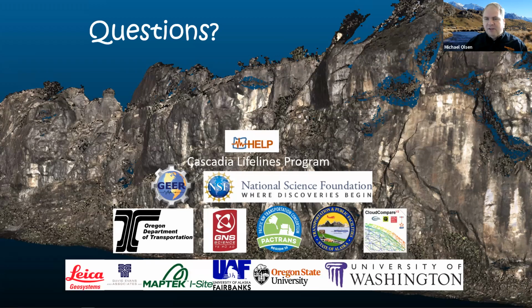The other is that with LiDAR, you get intensity information, which is the return signal strength. You can use that to make some estimations of the reflectance of the material after you apply some corrections. There are researchers, say at the University of Houston and Queens, that have been using hyperspectral data in conjunction with the LiDAR data, and have found that to be very effective for detecting different types of rock classifications. But there are generally limits. You may be able to detect sandstone from schist and other things like that, but beyond those basic categorizations, it can be very challenging. Great, thank you.